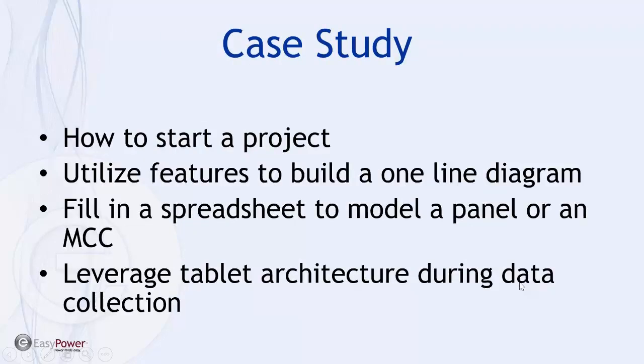So now, at a bare minimum, there's a certain amount of data that's required for short circuit and arc flash, and those forms are built into the OnSite defaults. But by adding a few more equipment details, which can be done in notes and can be done in the templates by modifying the templates themselves, we can actually expand the capabilities and the value added of doing the data collection by incorporating this additional information in terms of asset organization, tracking, maintenance files, and the like.